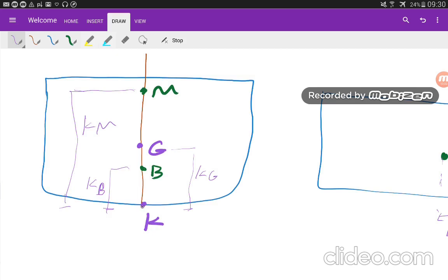At the bottom of the ship is our keel, and we name it keel point or K. We use the keel point as reference when we look at the midship cross section, and that's for transversal stability. One of the important points we have here is our center of gravity, which is G, and the distance between center of gravity and the keel point is KG.